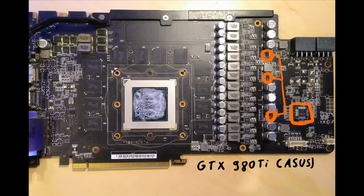And what that means is that the PWM controller can only be a 6-phase, can only be a 6 PWM signal controller, because what it does is it sends 2 signals to each doubler, and then the doubler will make 4 out of these. And that's how you get to all those 12 supposed phases that you have. So this is actually a doubled 6-phase on this card.